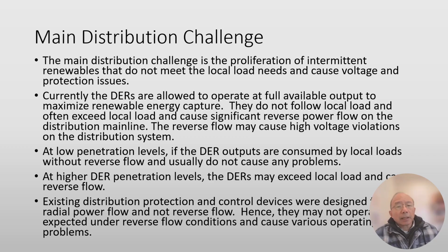Currently, the DERs are allowed to operate at full available output to maximize renewable energy. They do not follow local load and often exceed local load and cause significant reverse flow on the distribution main line. The reverse flow may cause high voltage violations on the distribution system.